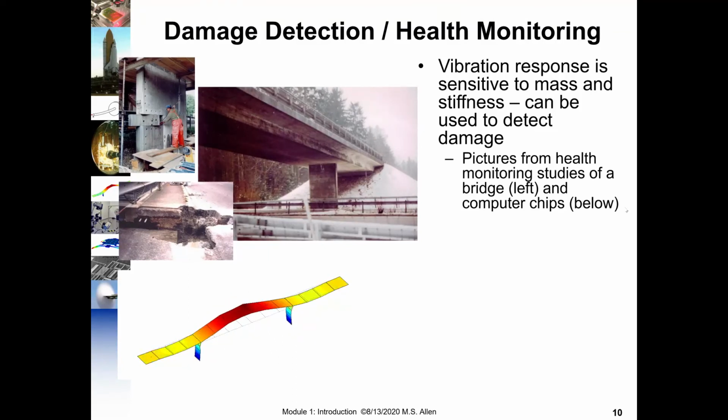Vibration is also used to try to detect damage. This was actually part of my PhD research. I took measurements that someone else acquired from this highway bridge in Switzerland. So this is an animation derived from the measurements. And they took measurements and then they did various damages to the bridge. The bridge was going to be taken down anyway to make room for a bigger one. And so they did little bits of damage and then repeated the test, and from that we're able to show how the vibrations change with damage and whether or not you could use vibrations to detect damage or have an early warning that the bridge might be near failure.